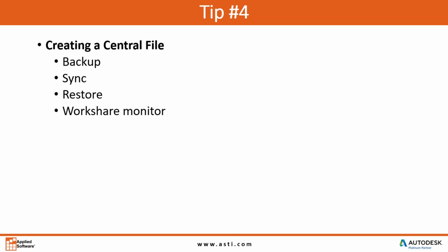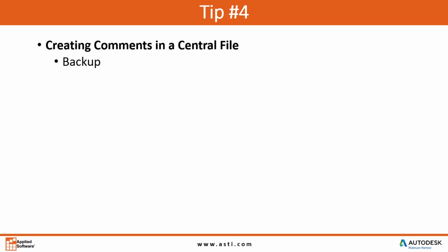And again, knowing that there's a wide variety of experience levels in here, we wanted to share some of these things with you. So one thing is the backing up of the central file, even a local file. You have something called my project.rvt, right? And you hit save or sync and all this other stuff, and it makes this .001 backup, which is a full live backup, right?